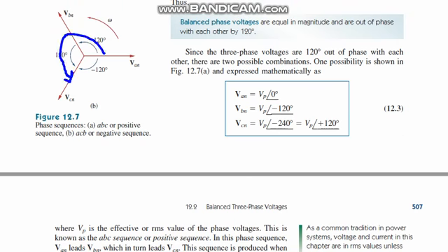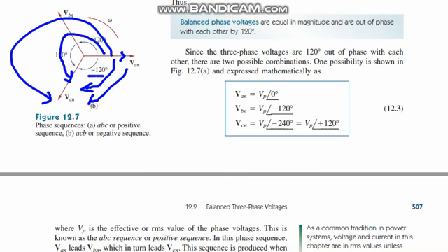That means if you just go through the nominal way, that will be minus 120. You can write both, because in these phases you can go through here and you can go through here too. Both sides are open, so you can say that will be 120, 240 degrees according to the negative sequence, and you can also say minus 120 degrees. That is possible here to understand this.